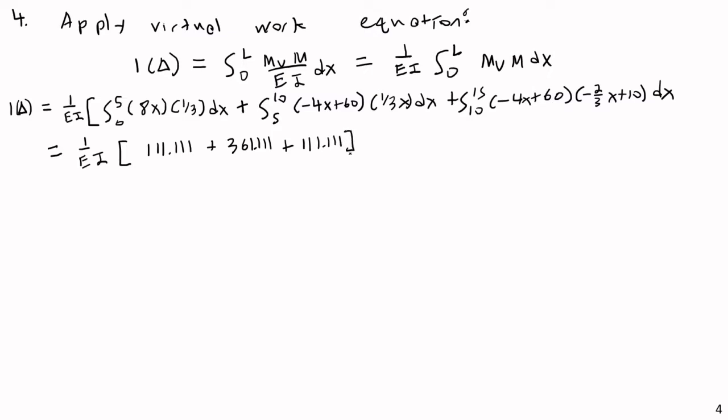And I would like to list the units on this. So moment fundamentally has units of kip feet. So I know this term must have units of kip feet. I didn't carry my units all the way through, but I do know that this should have had units of kip feet, and this should also have units of kip feet.